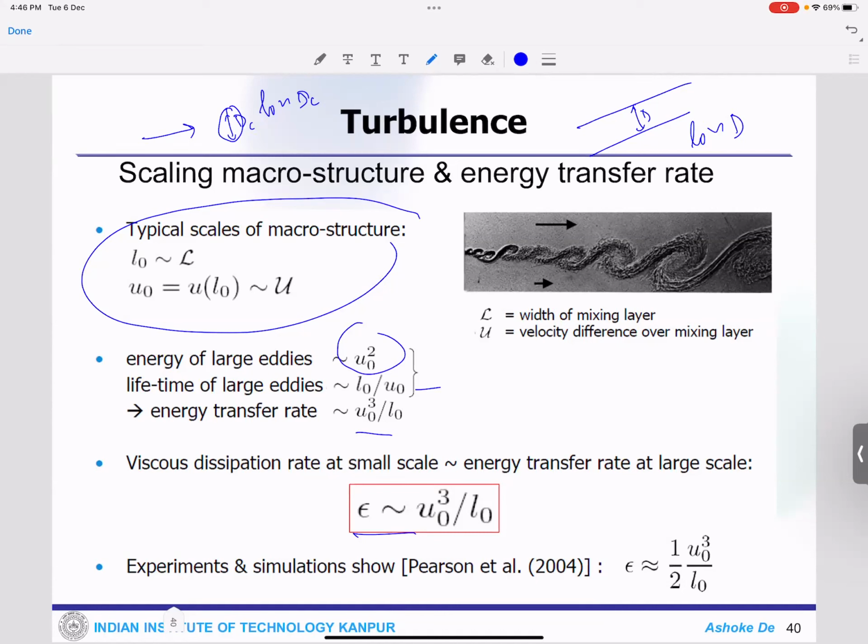Since I was just considering incompressible flow, I have not shown that term. So the vorticity transport equation is still valid, but there will be one more extra term on the right hand side. That becomes active in a variable density flow or a reacting system. In a reacting system, that term is going to play an important role. Okay.